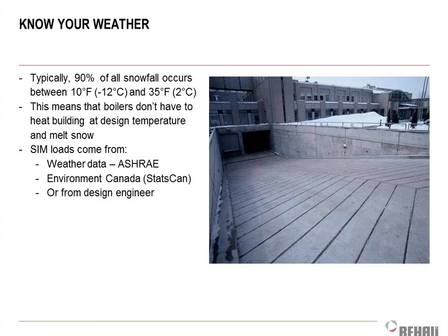The good news about that is that my boiler system for heating my building is probably designed for a 0 or -5 or -10 degree day. So the time that it's going to be snowing and I'm going to be melting snow is not typically my design heating day. That means in most cases I don't have to upsize my boiler. I can use my existing boiler and just grab some of its available heat to go melt my snow.